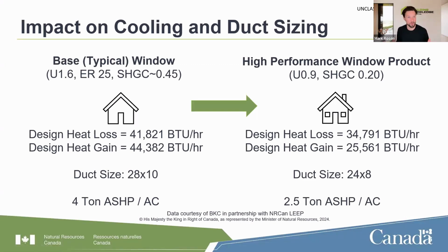That being said, there's an opportunity here for a bit of a shout out to the integrated design process that Lynne mentioned earlier today. It's very important as you plan your renovation project that your mechanical designers and contractors are aware of what your window selection plans are, so that as they're recommending a sizing of equipment, they're using the right numbers for their solar heat gain assumptions and their U value assumptions.